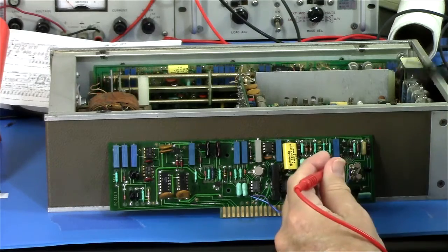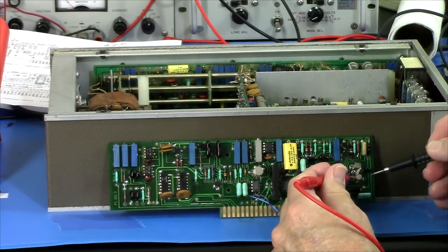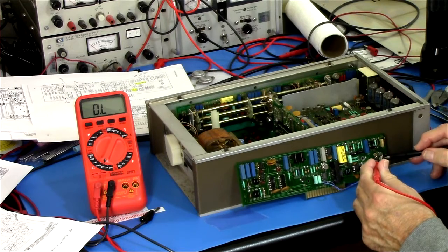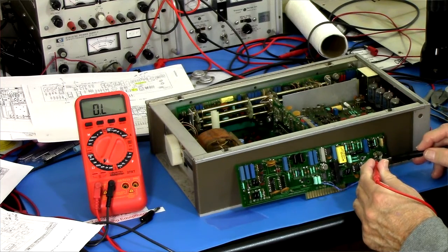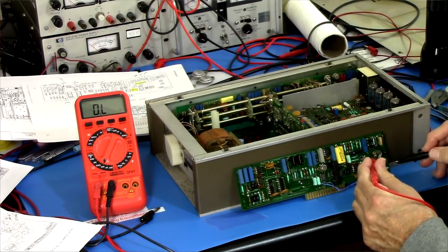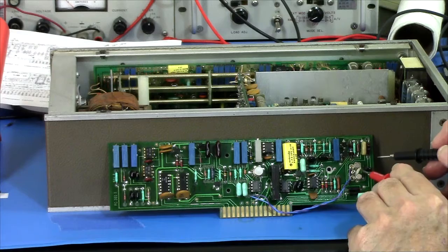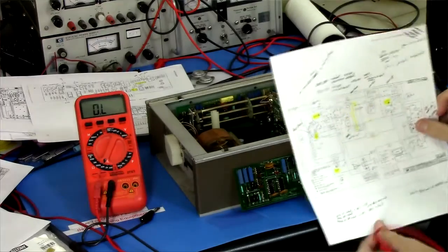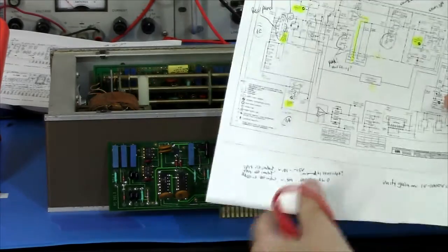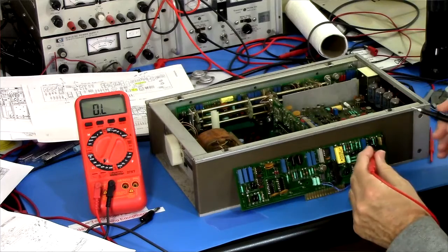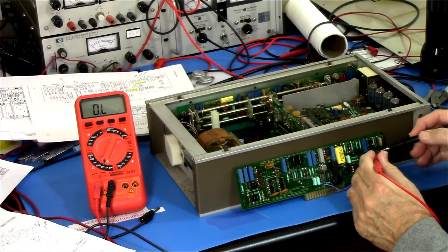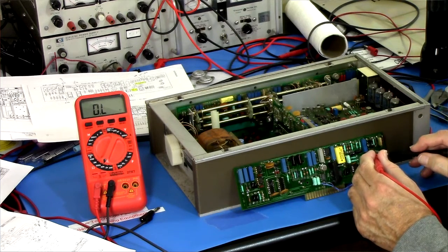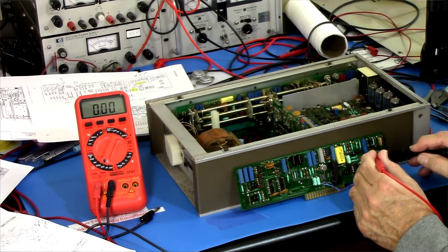So let's measure between the gate and the various connections. Okay. This one shouldn't have, well, neither one should have any connection between the gate and anything else. So I should get OL across the board, and I do. That's good. This one likewise. Now this one, these two I think are connected together. Yeah, and you can see that here. So that's intentional. But what about this? Okay. Overload. Going to the center one now. No, I'm going to the bottom one.